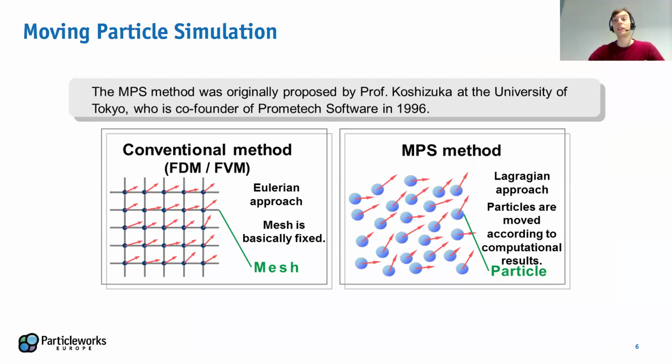So as mentioned, what are the key differences here? Conventional CFD requires a mesh, so it requires a user, starting from the CAD, to prepare the CAD, maybe clean up the CAD, remove some features that could not be easily meshed, and it requires a lot of pre-processing time.